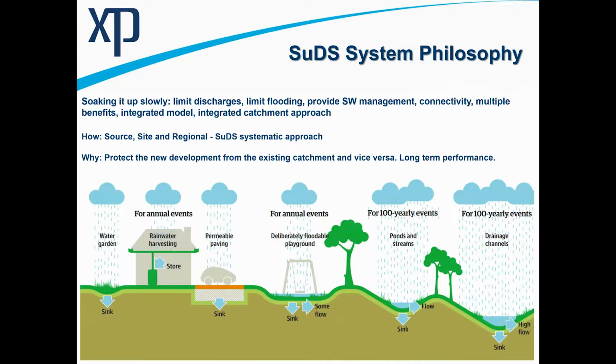What we also need to do is look at those extreme events. We're having to help communities now that are at risk to flood. So we're looking at the provision of surface water management systems. And to provide this, we really do have, at the very concept, have to consider the connectivity. Where is the overland flow likely to run? And we covered this in earlier webinars.